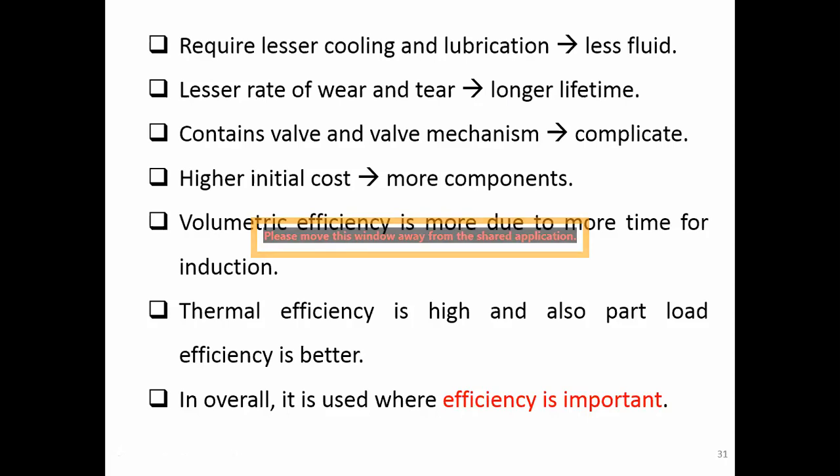Right. The gas exchange complicates the engine because it has valves and also a valve mechanism to control the opening and closing of the valves. Right. More expensive because more components. Okay. The volumetric efficiency is higher because there is more time for induction, right?